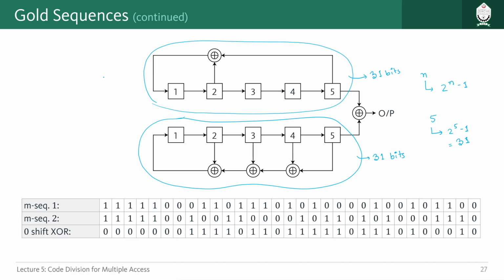Let us call this one LFSR1 and this one LFSR2. From LFSR1, this is the particular sequence generated. You can check it yourself. And for the next LFSR, this one, this is the generated sequence. Already these two can be considered as two Gold sequences among the number of Gold sequences we will generate. So these two are the first two members of that family. Now how do we get the new members, new Gold sequences, from this particular circuit? To do that, this XOR gate comes into play.